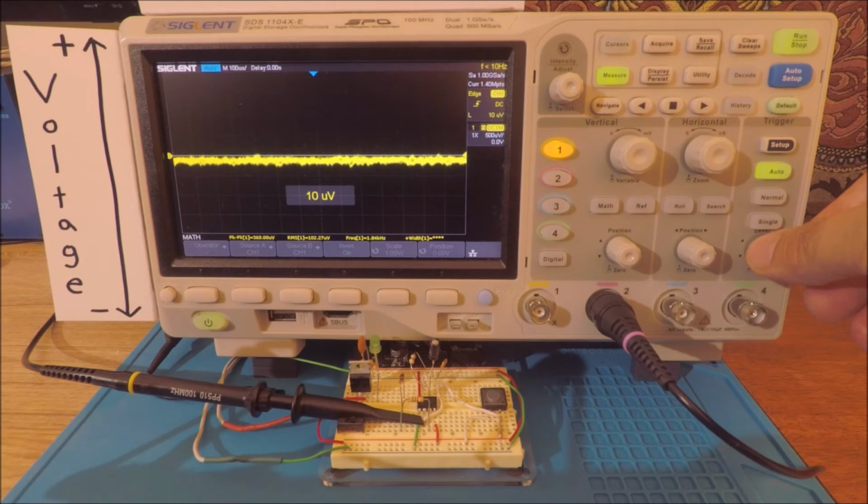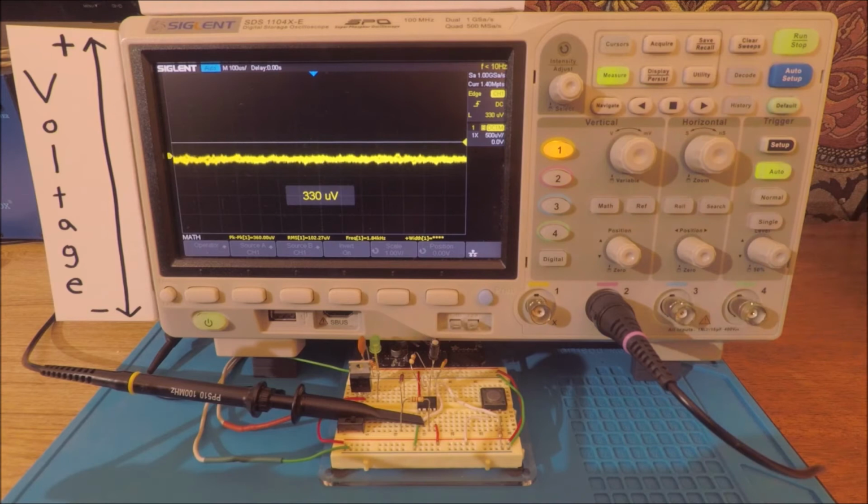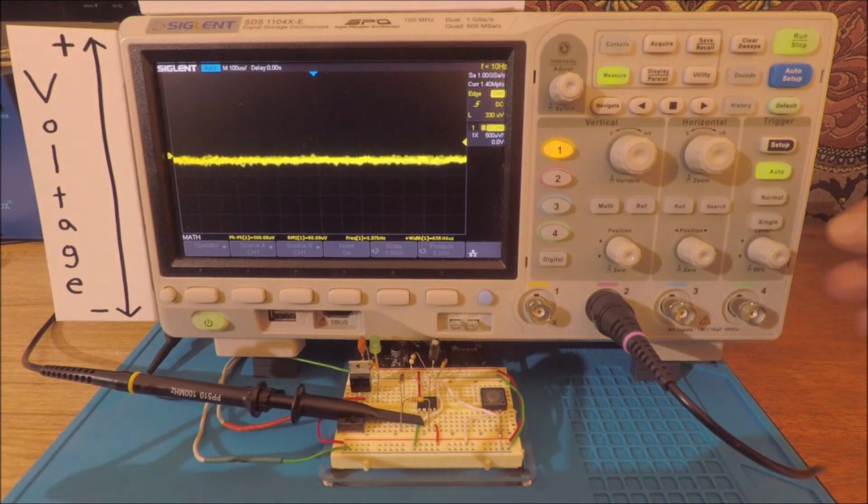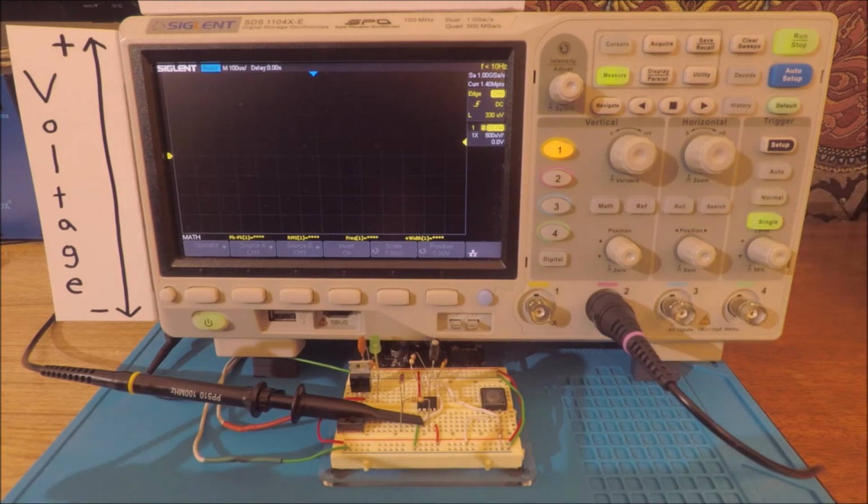And we had a threshold that was at 0 volts. I'm now going to move that horizontal threshold up and out, maybe just a few hundred microvolts, just to get it up and out of the noise floor. Like this. Now we're still in free running mode. So what we're going to do now is change and place the trigger into single shot mode.